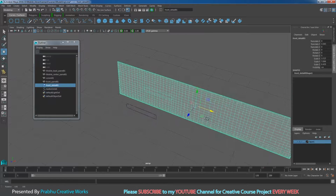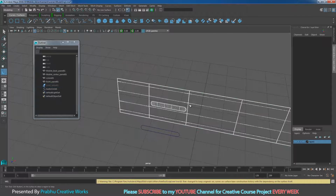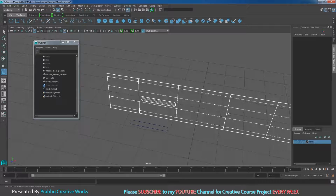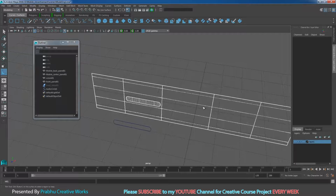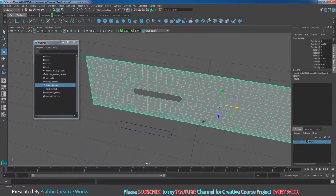So I will select my node's detail, go to surfaces and choose trim tool. So click anywhere on the outside, don't select the inner part. So click anywhere on the outside and press enter. So that means you got a virtual hole on your object.